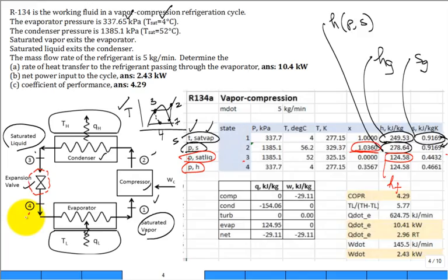People question me about that all the time. Can we have an isentropic efficiency for a turbine? I mean, an expansion valve? Yeah, I've never seen one defined. What in reality, though, is you will have a little Q dot either into or out of that device because if it's cold, the surrounding room is a little warm, there will be a little heat transfer. But basically, it's such a small area that it's a very small amount of heat transfer, and you neglect that heat transfer.